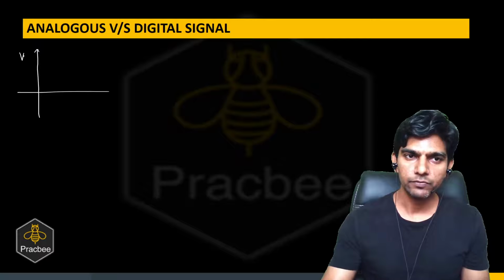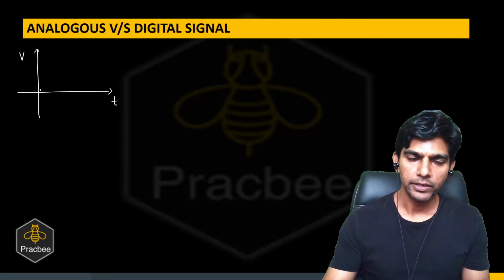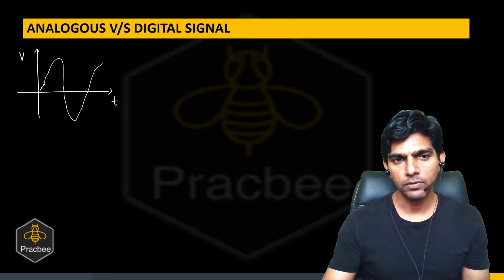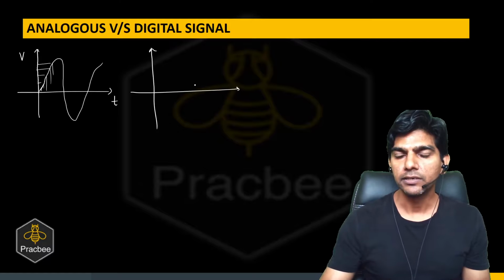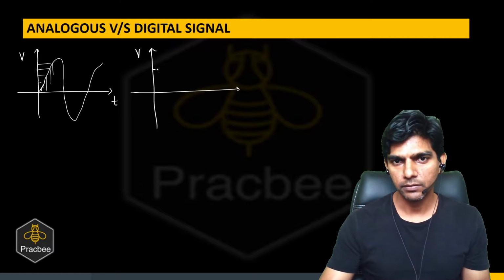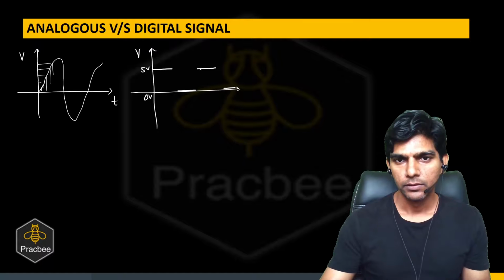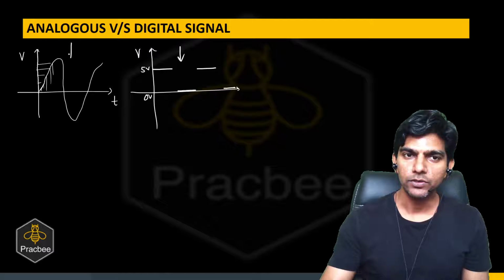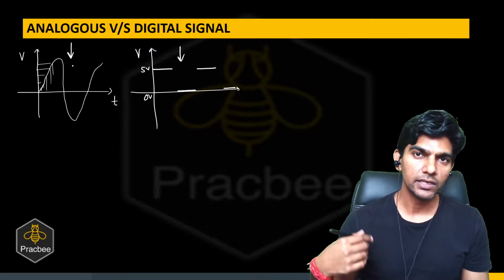If there is a signal, say a voltage signal, which is varying with time, it can have any value, right? Something like this. So it can have continuous values, different values at different times. And there is another signal which can take certain discrete values. For example, it takes 5 volts or 0 volts, 5 volts or 0 volts, right? So there are only two possible values. So such a signal is known as a digital signal. If we have continuous values, such a signal is known as an analogous signal.